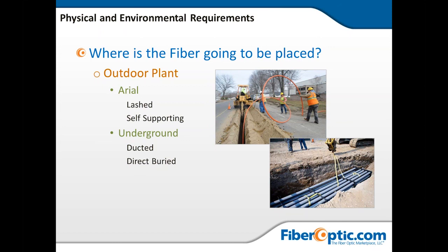They also owned the power company, so they had access to the neutral space above joint use. By using self-support, it was all dielectric, so we could safely, within the standards and with the proper installation technicians, install this fiber in the neutral space above, where joint use installers are allowed to operate. And it freed up a great deal of space because they used self-support. We could not put conductors such as strand and lash up in that space.